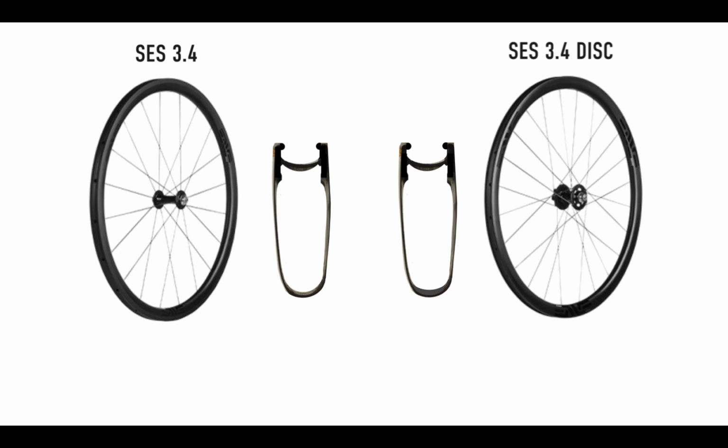Critically important, the rims are not interchangeable. This rim here is made only for disc brakes, this one only for rim brakes.